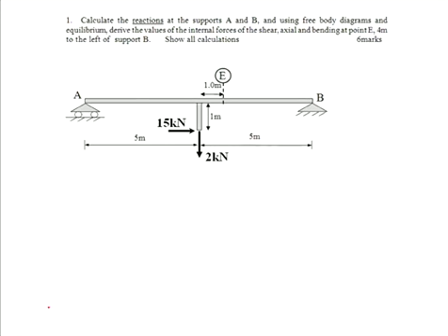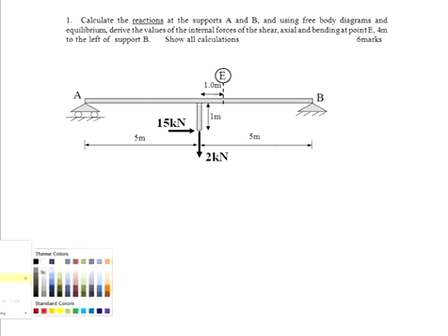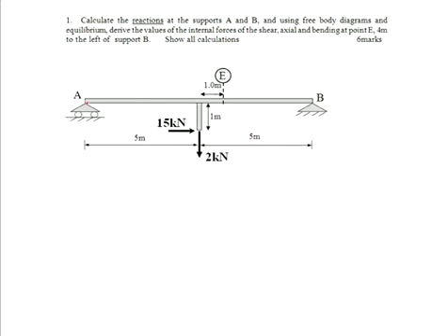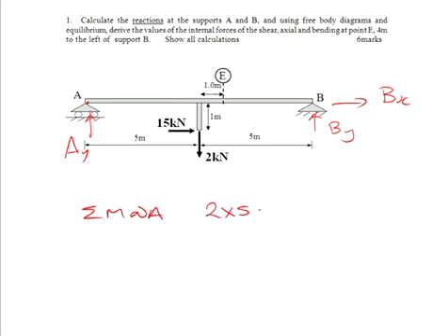Okay, question 1, I will not do the entire question here, and I covered this effectively already when I did the equilibrium equation. Where people went wrong, when they put their unknowns in here, bx, by, ay, and they took moments at A. Everyone, I think, said, okay, it's 2 times 5, vertical load, horizontal distance, it's going clockwise. And then they looked at by and said plus 10 times by equals 0. And what you did was you forgot about the horizontal force.